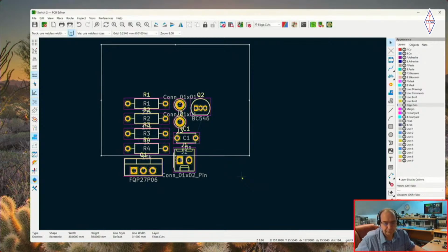So again, to remind everybody at home, at this stage, all those components that you put there, because you spent time choosing the right footprint for them, not just the right schematic symbol, but the actual footprint, that means that these are already representing their real scale size on the circuit board. Exactly, yes. And again, there's a grid to the circuit board, so when I come to position them, I can position them where I want. And I don't know if you can see, but very thin lines have appeared. Those are the net list, the nets, which show what's connected to what.